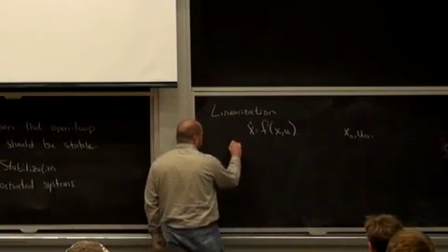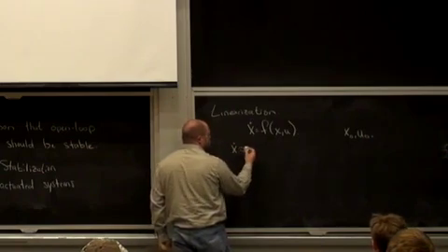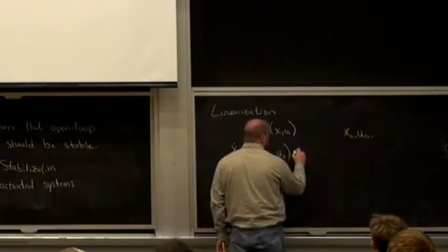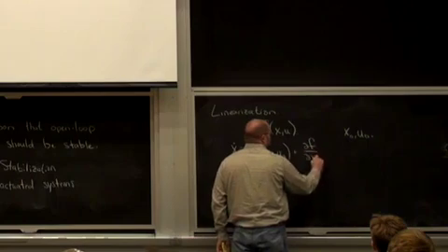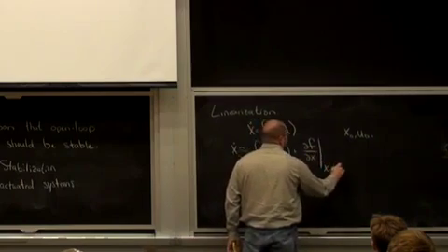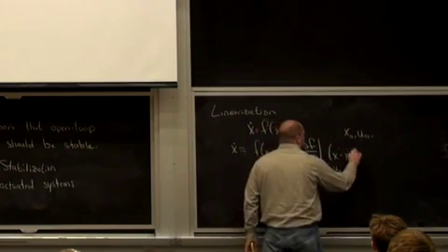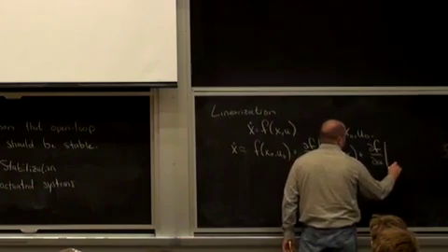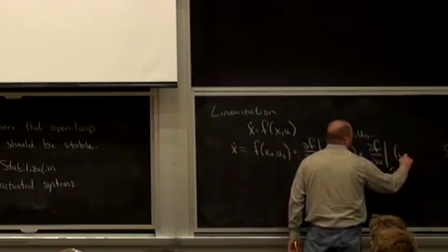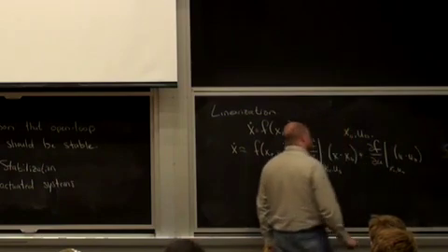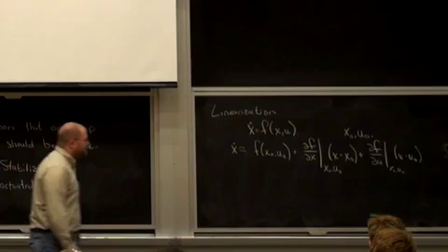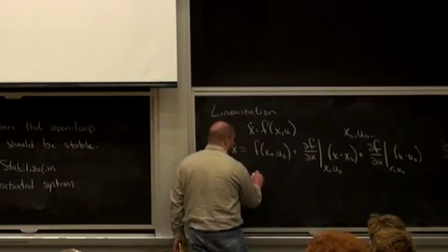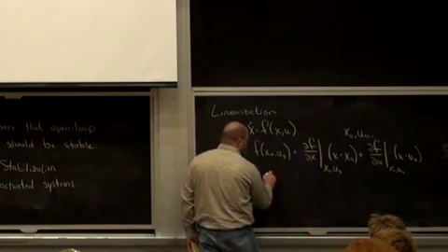The Taylor expansion of this says that this thing's going to be approximately f of x0, u0, plus partial f partial x evaluated at x0, u0. Okay, and we called this before A and this B, and so that thing we can actually write as, in general,